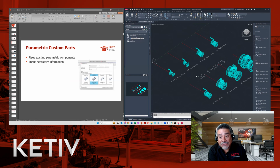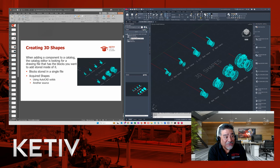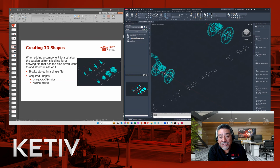The way I lay these out too, let me jump up over here, kind of follow through what we're going through here, is that once I get these in here, I kind of like to keep a reference drawing first of these items. So I'll go through, I'll put some reference points on, construction lines or where these insertion points are at, where the actual outside, the furthest out part location of this valve. That way I can do my port connections on this, and I'll show you that in a little bit.